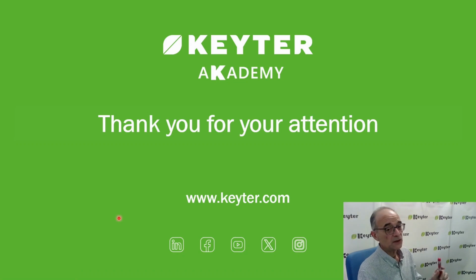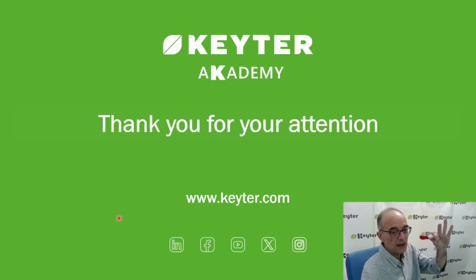That's all. As you have seen, the concept of SEPR compared to SEER and SCOP, apart from the fact that SEPR is only for cooling mode, is somewhat different. It's different because of the number of hours it operates, and it's also different because it includes that concept that, as you may have noticed, it will operate between 80 and 100% most of the time. So these are systems that will be operating very close to or almost always near their nominal conditions. All right, see you in the next video where we will look at the ETAs, the seasonal efficiencies.